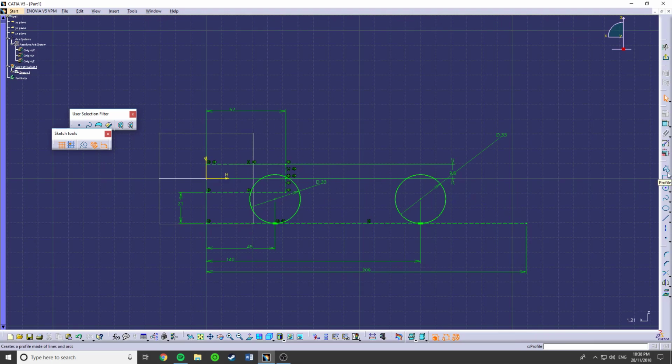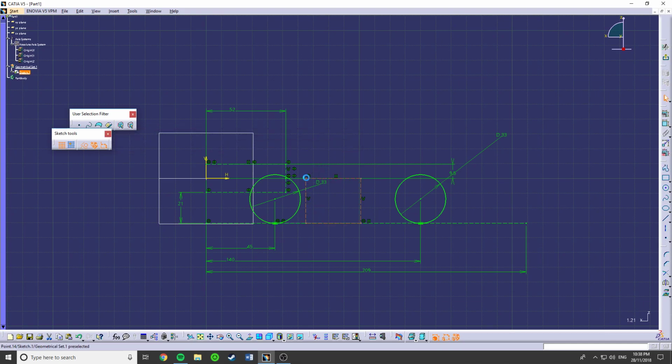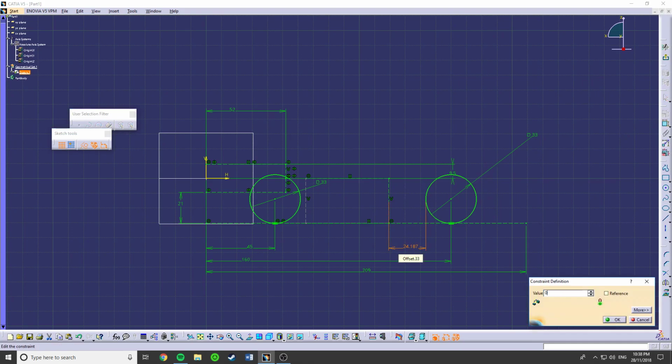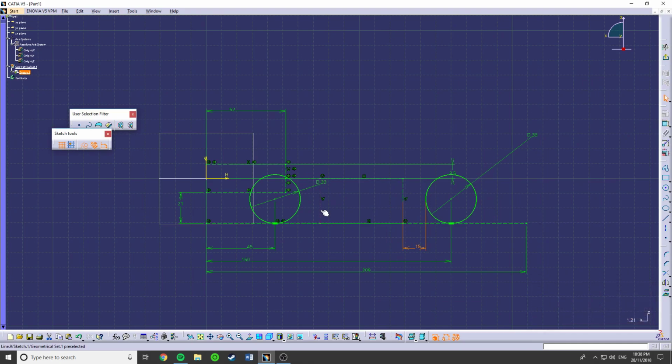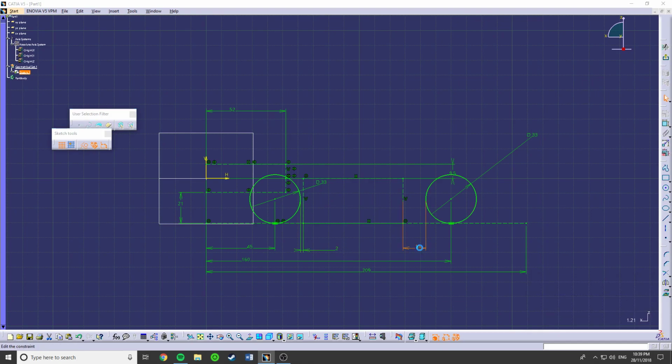So now this is where, by choice, you can allocate zones. I'm going to go back to construction, and I like to allocate zones where my stuff can be. So say maybe a side pod here. Side pod's pretty terrible actually, so I might increase the wheelbase. I'm going to make that 160. So I define a side pod and it has to be 15 away, and we'll make that 2 millimeters more because there's no tolerance, so actually we'll make that 17.